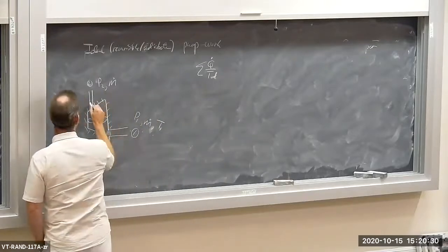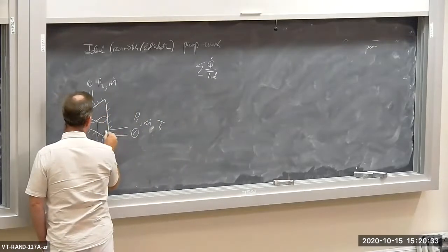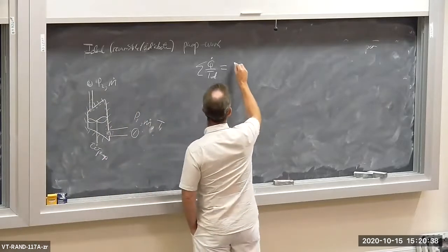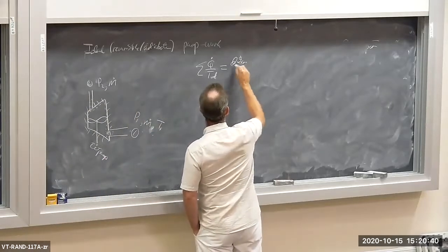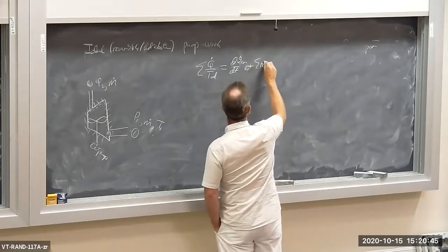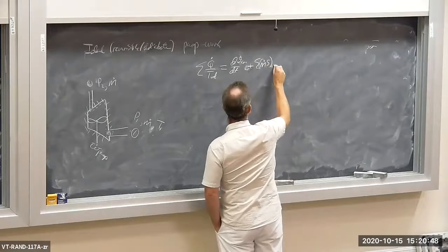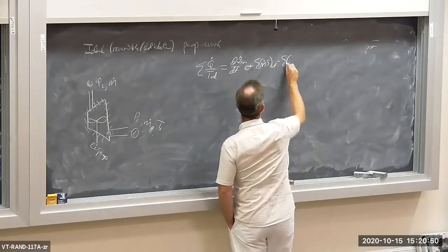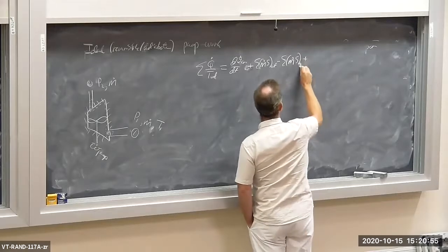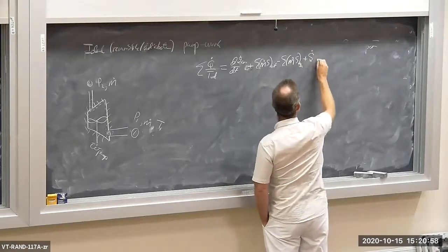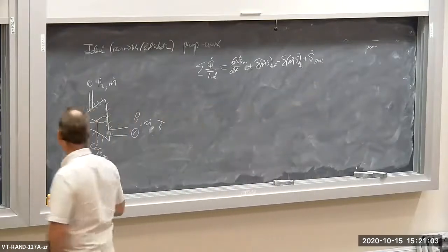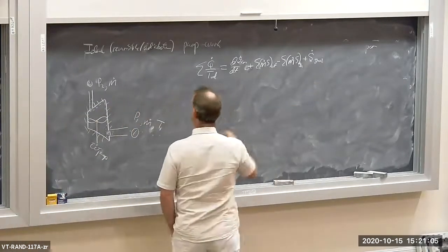So my pump, here's my open system. So Q dot over T is equal to dS within my control volume dt plus the sum of the mass flows times S out minus the sum of the mass flows times S in, and then I've got S dot gen, okay? Open system entropy balance. So it's adiabatic.